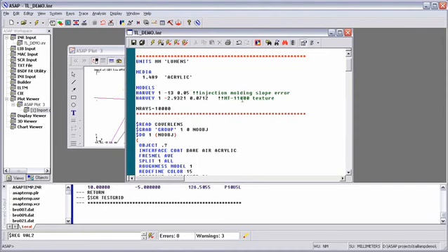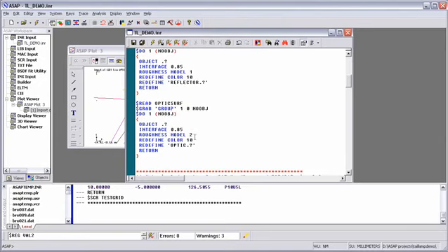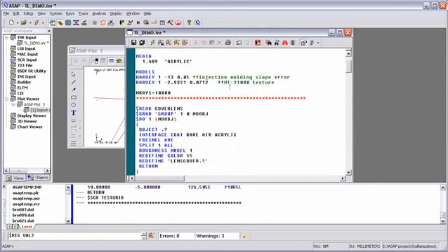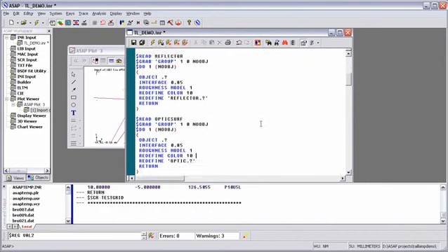The other thing I've set up in this file is a texture. For those of you familiar with injection molded parts, a lot of times they'll put on something called stipple or Mold-Tech finishes. In this case, I've simulated that reflector using that texture. If I wanted to find out what the performance is without that texture, I simply have to change my model back to just the bare molded slope part, and I could rerun my simulation and have that result.